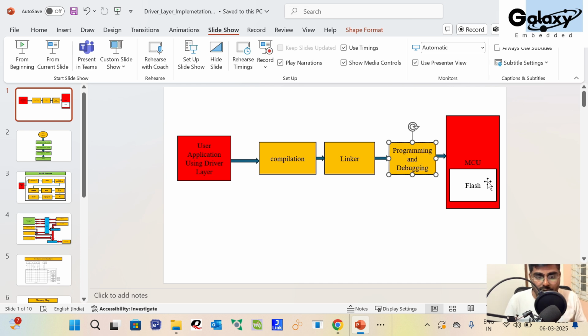In this course we will not use any IDE. We'll write our code in notepad, we'll write a linker script, we'll write startup code, and we'll write makefiles to compile all our .c files. We'll do everything from scratch. Debugging also we'll do by using openOCD command lines. So this is the program flow.